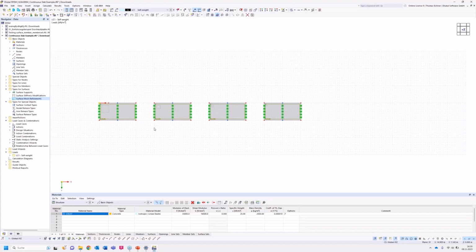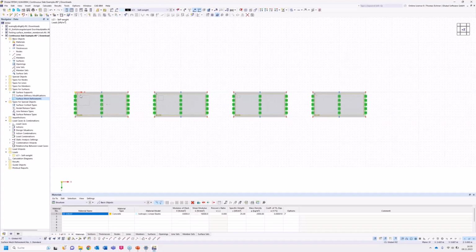And yeah, now we can also see these squares in our surfaces. And those show us how the mesh size will be. Like this will be very coarse and this will be extremely fine. You could estimate this will be roughly 1,000 times more elements than the first one. Not 1,000 times the calculation time, but let's say 5 times the calculation time. It's just an estimation.